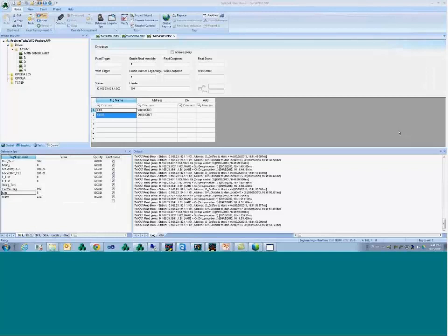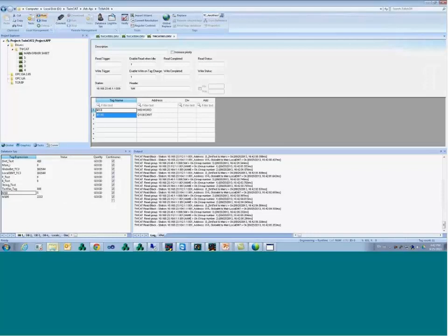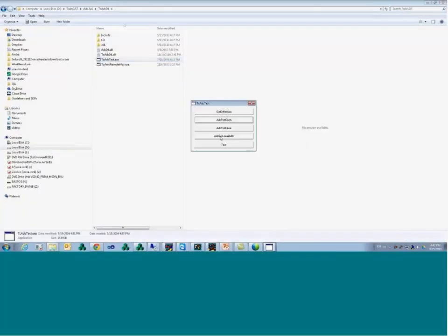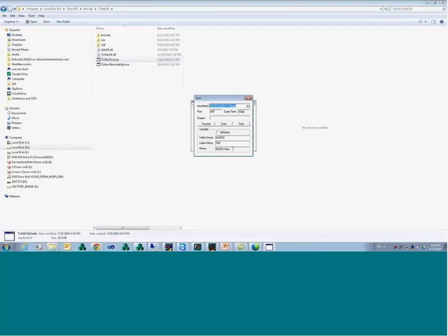Okay, why are function block parameters not accessible on TwinCAT 3? Again, whenever you have something that doesn't look right on our driver, you go back and you use this guy here to test. You can open the port, test, and here you put how the parameter syntax is. If this guy fails, that means that the ADS may not support that. If this guy works, the driver is going to work as well.